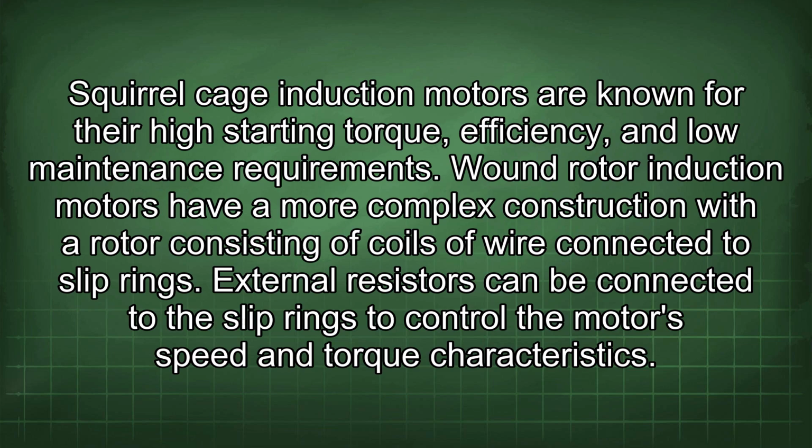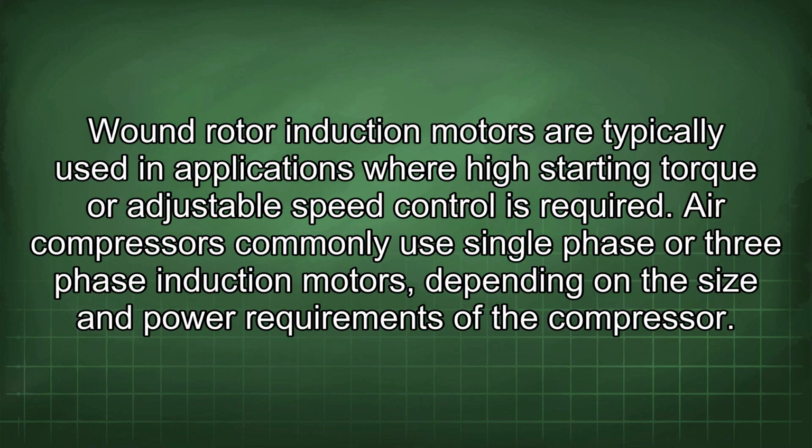Wound rotor induction motors have a more complex construction with a rotor consisting of coils of wire connected to slip rings. External resistors can be connected to the slip rings to control the motor's speed and torque characteristics. Wound rotor induction motors are typically used in applications where high starting torque or adjustable speed control is required.